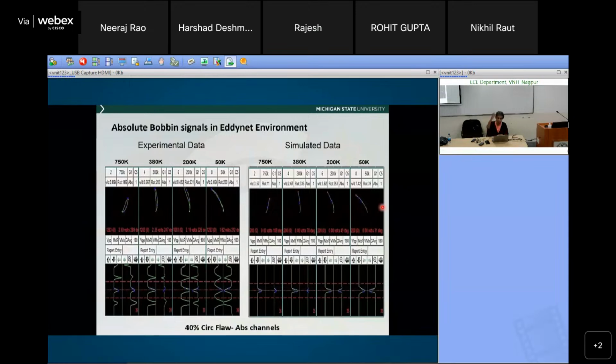So when the probe goes past the defect, the front edge is different from the back edge. So you have slightly different opening of this signal. The impedance traverses this path up to the maximum, and then the return path is not identical.